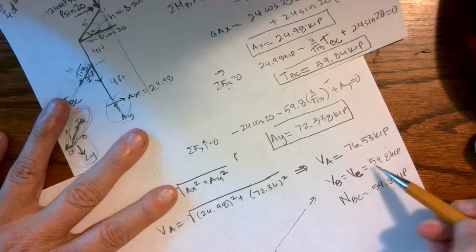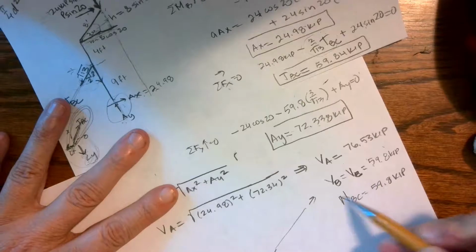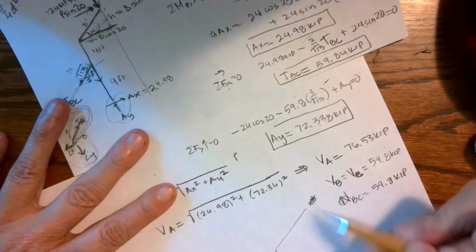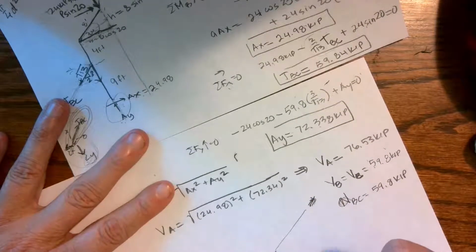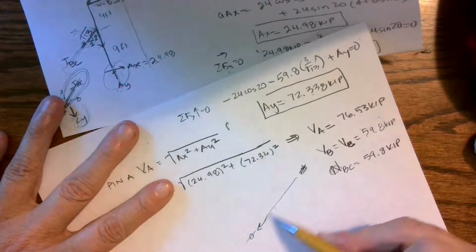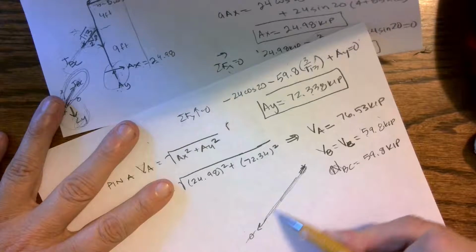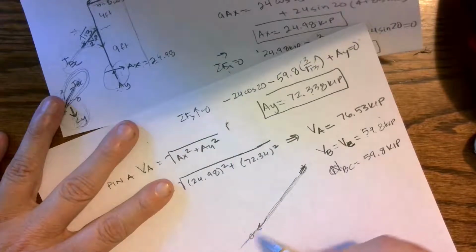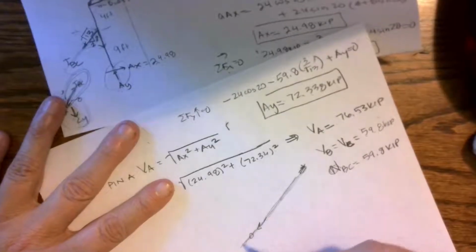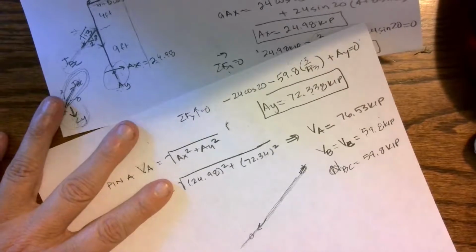When it's acting perpendicular to the shear pin, it's that normal force that becomes, here's the cross-sectional area, it becomes shear. Okay, it's normal. We're pulling this like a rubber band. As it passes across, it's going across the cross-section of the bolt. It becomes a shear force. So these are going to be the values that we design with.